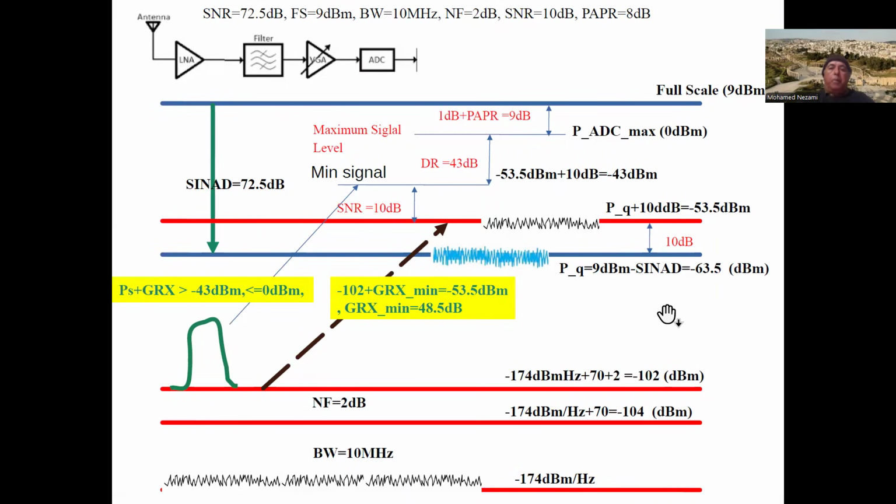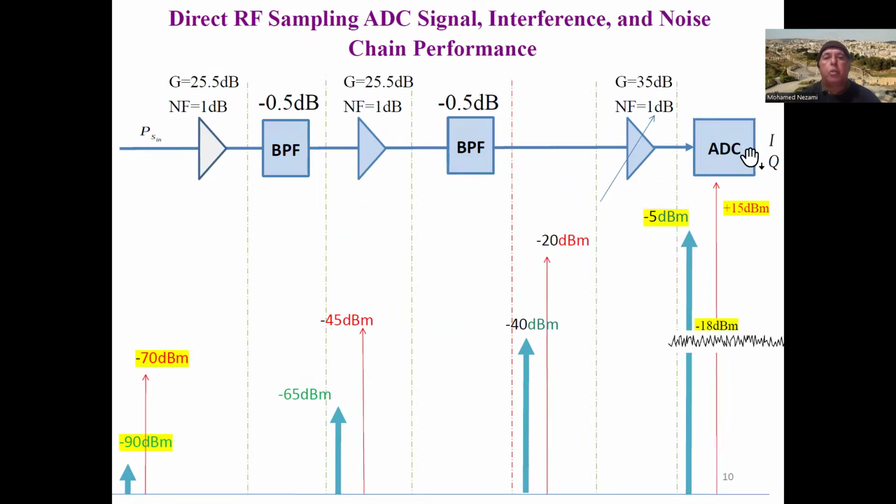So let's look at another example of how we budget the ADC issues with this signal without the interference. In the coming lectures, we're going to come back to this and say, for instance, we're going to have aliasing of both the noise, because we're oversampling a signal that is beyond the Nyquist frequency. So we're going to get some aliasing of harmonics and the harmonic creation by the ADC or the amplifiers at the front end.